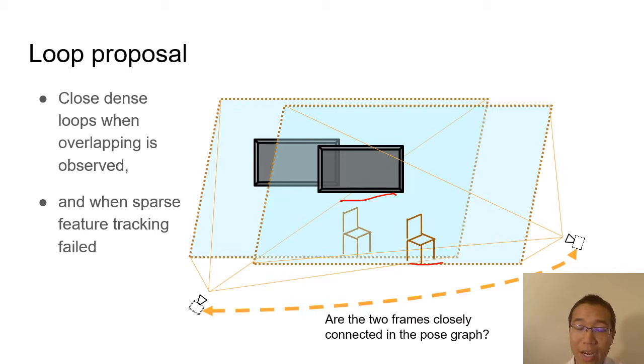For each camera observation, it will find all the different points, and then connect all the points it can see, and then connect the camera frames. If these two areas are connected through the visibility graph, then we say that's not a loop. If they are not connected, that means they should be connected, and then we propose that's a loop over here.